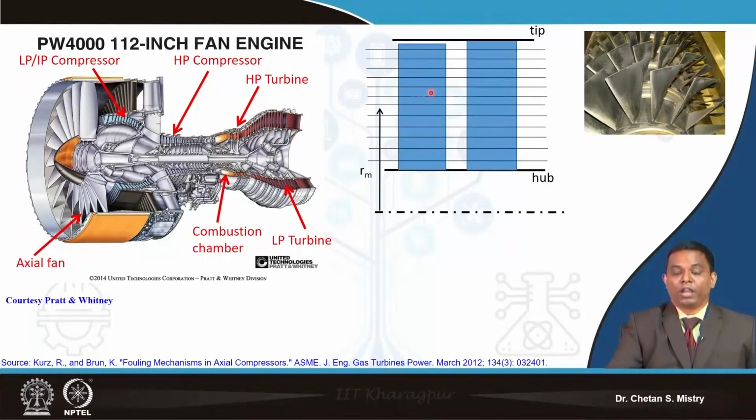Remember one thing: these blades of rotor and stator are made up of a number of aerofoils. We will discuss the meaning of the aerofoil, but here just look at this blade, it comprises a number of stations. At all stations we may have different aerofoils. They are stacked in a systematic way in order to meet the requirement.